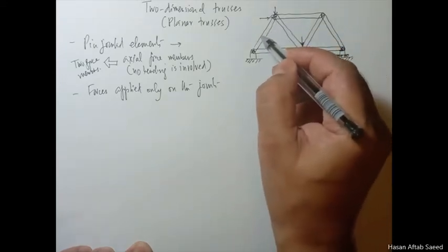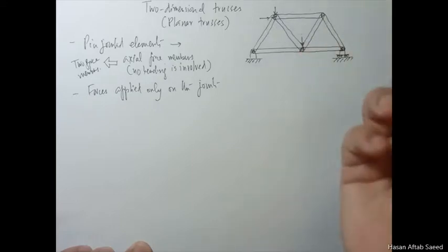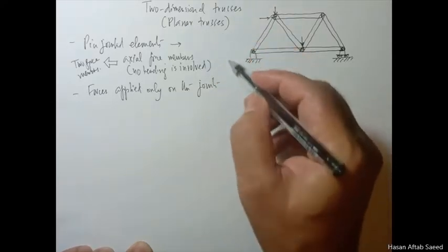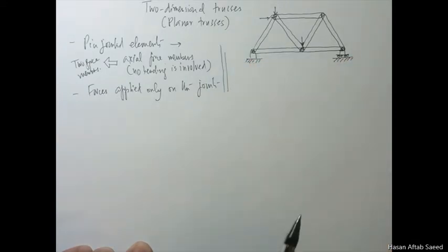There's no provision of force acting here, because if the force acts here, then by definition it's not a two force member, and then there'll be bending involved and all that sort of thing. We have elements to deal with that, but here we have limited our analysis to these conditions.